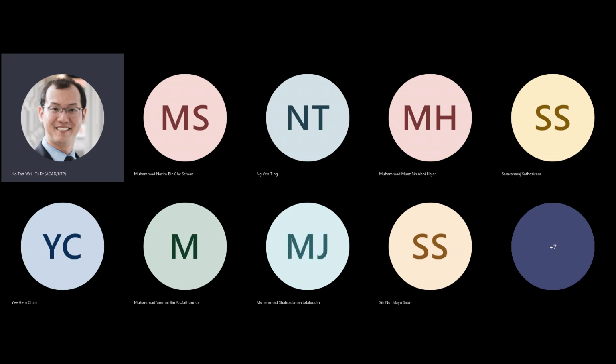And you can then check the logic operations. When this is 0, that means this switch is conducting. This 0, this switch is conducting. If both of these switches are conducting, the output is being pulled up to VDD. If either one of these switches is conducting, it's always pulled up. Only when both these switches are not conducting, that is when they have a VDD here and a VDD here, and these two switches are conducting, do you get this output pulled down to logic 0.